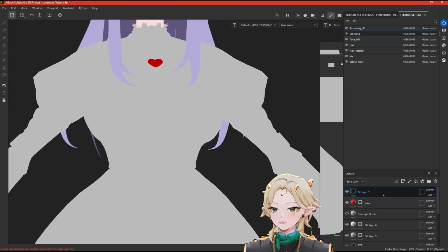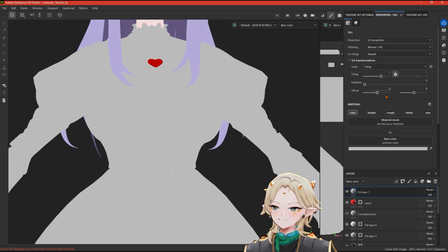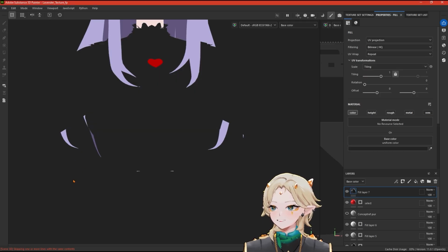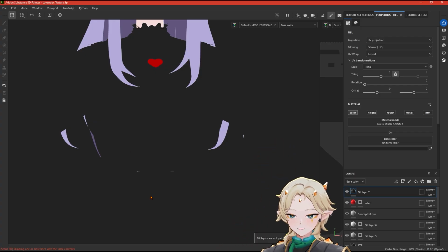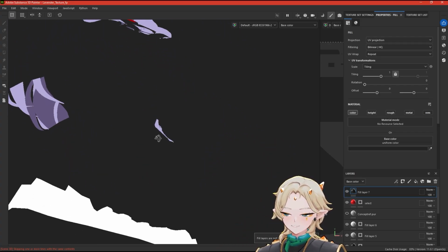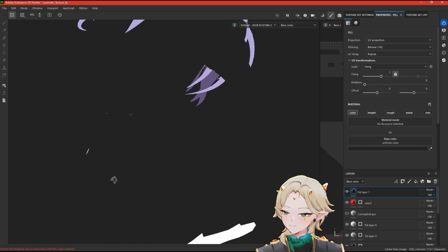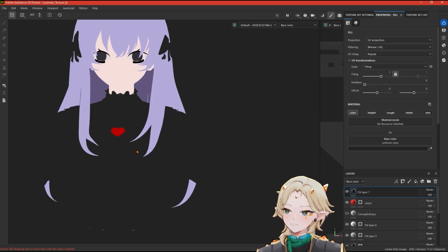Then above it, I'll create the opposite. The, hey, I don't want to paint on this. This is the layer of don't paint on this. Typically, if I just use the eyedropper here and select the background, it'll make stuff look invisible in the base color view because it's the same color as the background. That tends to work quite well for me. This is also a good way to troubleshoot geometry. If there are holes in your mesh you can typically see them, like I can see through the skirt in a few spots, and that might serve as a good way to clean up my mesh later.